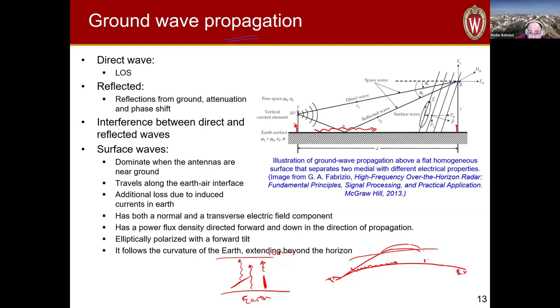And then when they come out, you'll get some sort of polarization rotation, right? You get a Faraday shift of that. So let's say you're transmitting your wave with a given polarization. On the other end, you may not exactly get the same polarization. The best thing that you can do if you really want to be capturing all the data or have a very reliable communication link would be to use maybe a vector sensing type antenna.